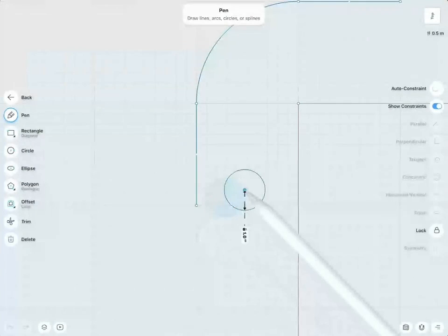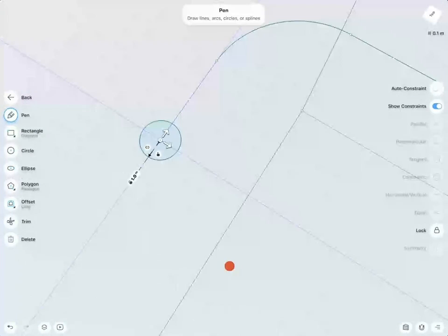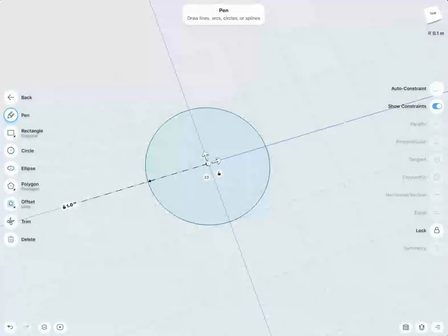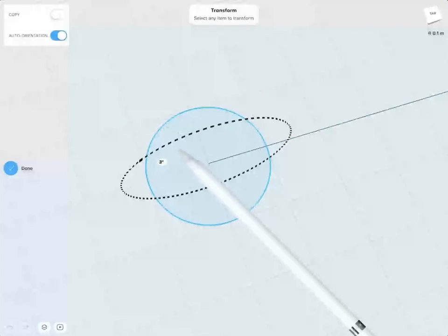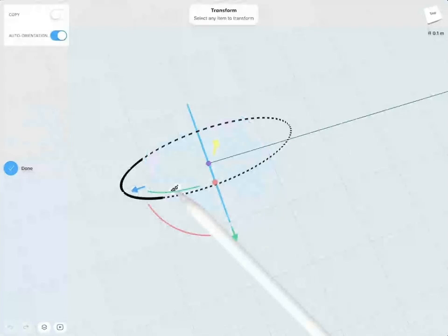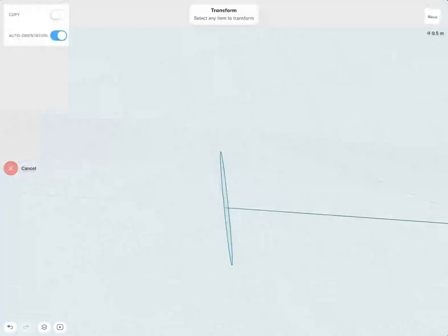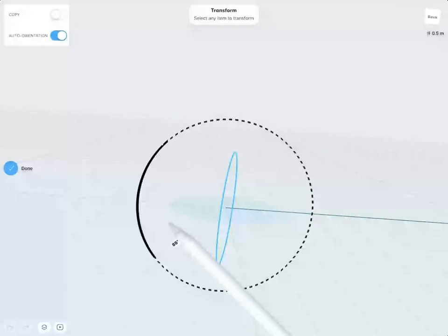And then this endpoint, because I'm still working on the same plane and in 2D, I snap this and then I simply rotate it. So essentially it's the same end result as using the construction plane. It simply saves me a little step. So let's rotate this one 90 degrees. No, that's not 90 degrees. Let's do this one more time. There. And 90. Very good.